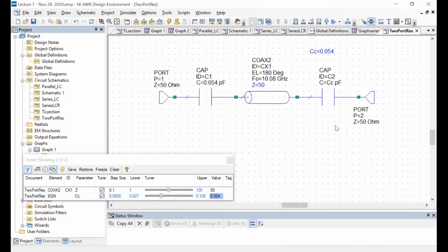Okay, by the way, I hope this idea that you might have to capture the reflected signal and the transmitted signal is obvious and clear to you, that there is something related to the resonator coming out of both sides. So you would ideally want to look at both of them to get the full information. Otherwise, you're just losing some signal to noise ratio. Now, that might or might not be an important requirement depending on the application, but often in qubit experiments, you're really starved of signal, so you don't want to lose any signal anywhere.